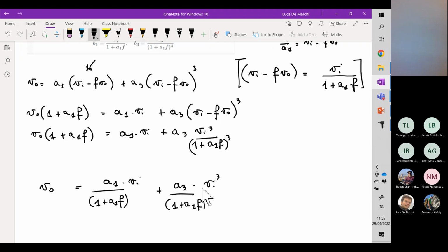So we would like to have a faster method to estimate the stability of the circuit, and this can be done by focusing on this T(s), which is the multiplication of A(s) times F(s), by virtue of the so-called Nyquist criterion.